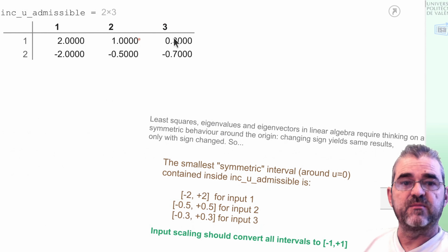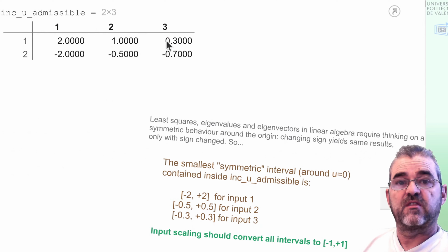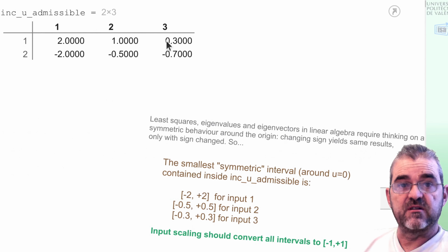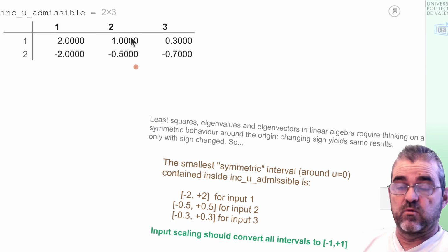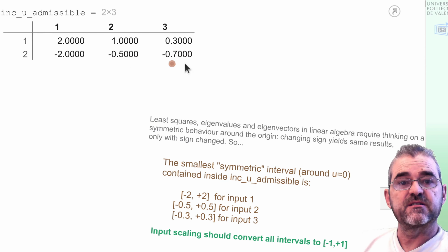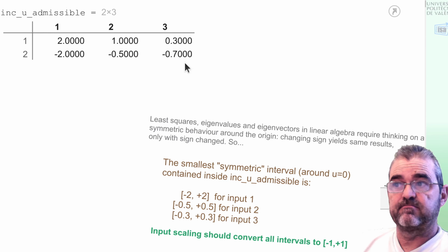These are the increments of input that are available to me. Then again, if I use the geometry of ellipses or spheres centered in the origin, the operating point, then the worst case is the minimum amplitude. Let us consider, for instance, manipulated variable 3.